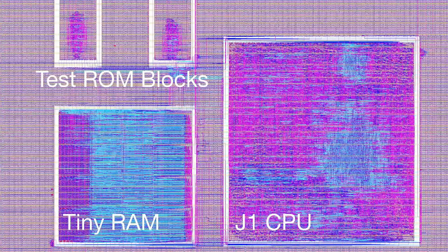I need register file blocks that I can rely upon. I need SRAM blocks. Like, this is ridiculous SRAM, right? There's not enough SRAM for that size. This should be 16 kilobytes. It's like 128 bytes. That is not a reasonable thing. So there's still stuff to do on the open side, but it's an exciting time because suddenly it's possible, and it wasn't possible before.